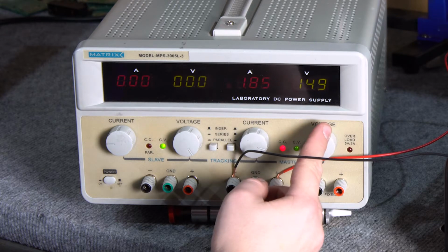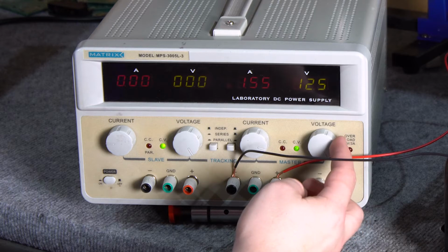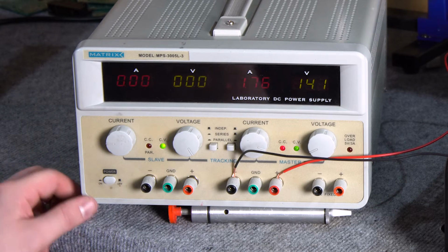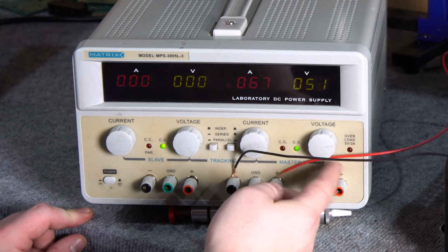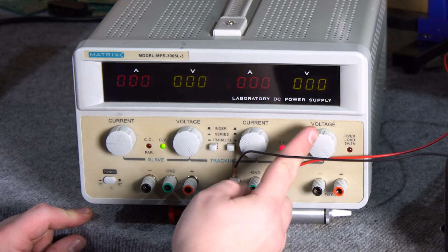However, if we anticipate that the system should take no more than 200 milliamperes, then no more current will flow through the system at the moment of short circuit. We can observe such a state by the fact that the output voltage has dropped, or by the change of the backlight of the controls from CV to CC.